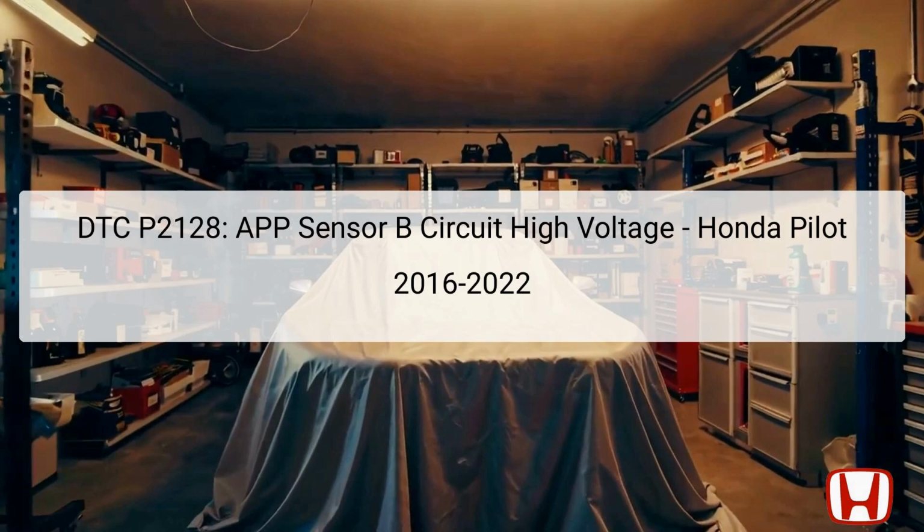The DTC P2128 refers to a high voltage condition in the APP sensor B circuit, specifically the throttle position TP sensor E. This diagnostic trouble code is crucial for ensuring proper throttle function in the vehicle's engine management system. If the APP sensor sends incorrect voltage signals to the powertrain control module, PCM, it can cause various performance issues.